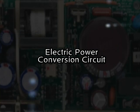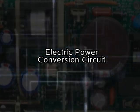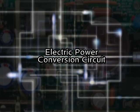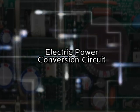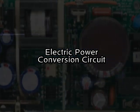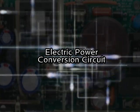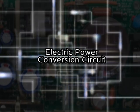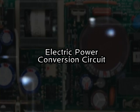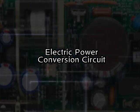All electronic equipment and apparatuses consume electric power. For example, a seawater cooling pump needs 3-phase AC voltage, while a fluorescent lamp needs single-phase AC voltage. Items inside telecommunications equipment and computers require voltages of 42 volts, 12 volts, 5 volts, and 3.3 volts DC. However, many generators installed on ships output only 440-volt 3-phase AC voltage. As such, many devices cannot directly use voltage generated by shipboard generators.